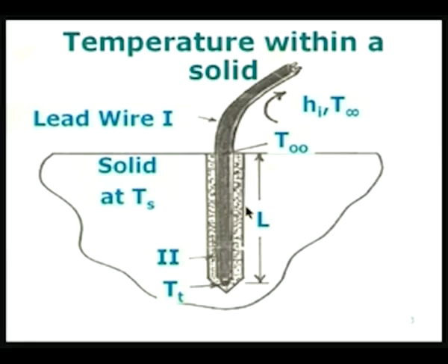So, we can use some material which conducts heat effectively, so that there is a good thermal contact between the thermocouple and the walls of the hole drilled into the material. We will see how it is going to affect the measurement of temperature. And of course, the lead wire has to be taken out, there is no other go. The thermocouple is taken out and it is probably exposed to an ambient at T infinity, that is shown here, and maybe some amount of convective heat transfer is taking place between the outside of the lead wire and the ambient.